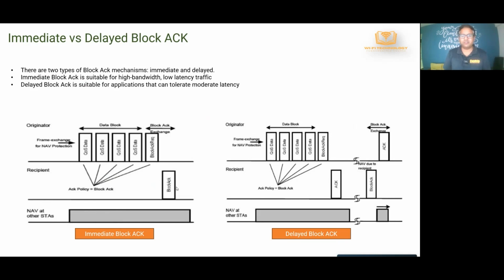The receiver needs to process all of them, do all the error calculations, everything in each one of them, and collect all the data, and then create the block ACK acknowledgement within a short interframe space, within a few microseconds, literally. So the receiver's computation power should be really, really nice. And this is why this is all done in hardware, right? And the reason why you do this in hardware is because you have to be very, very fast.